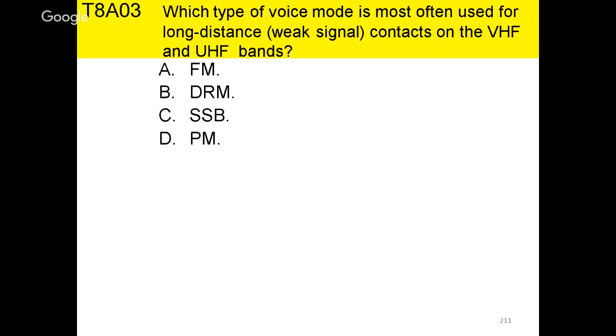It had 40 AM channels, and it had 40 lower sideband channels. It had 40 upper sideband channels, but these were all pretty much shared frequencies. It also showed that, well, here you go, on sideband, you can transmit 12 watts instead of the 4 watts. Well, there's a reason for that. It's still the same power. It's just how they configure the power as it transmits and where it concentrates that gives you a 12-watt ERP, or effective input to your antenna.